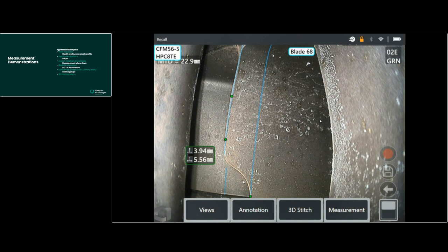So a number of hours were taken, probably 4 or 5 hours taken to remove this material here and remove the site of high stress concentration associated with either a crack, a tear, or a nick. In this case, that was close to the tip of this aerofoil.